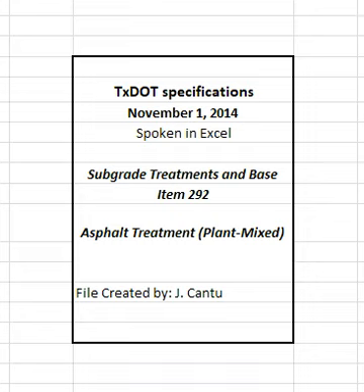Certify compliance of the RAS with DMS 11000, evaluating and using non-hazardous recyclable materials, NRM, guidelines. If the RAS has not come into contact with any hazardous materials, treat it as an established NRM. Use RAS from shingle sources on the department's MPL. Before use, remove substantially all materials that are not part of the shingle, such as wood, paper, metal, plastic, and